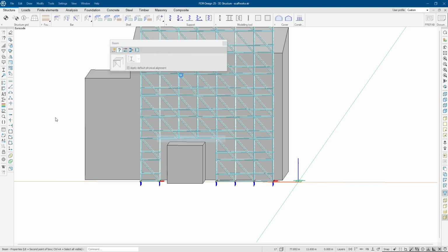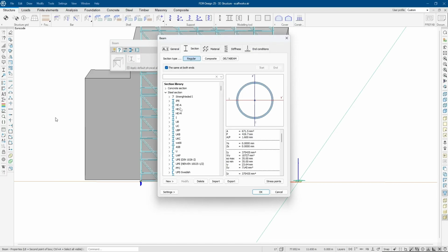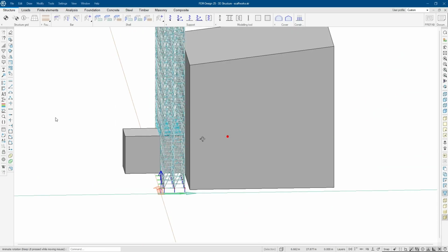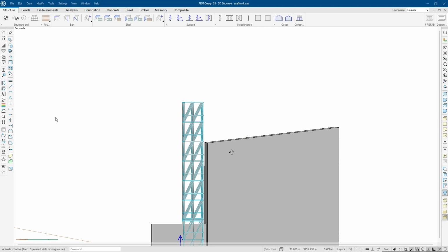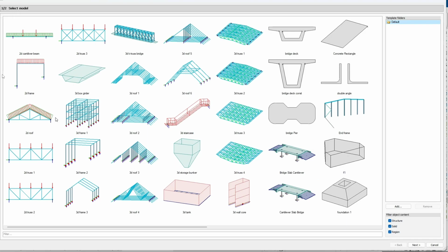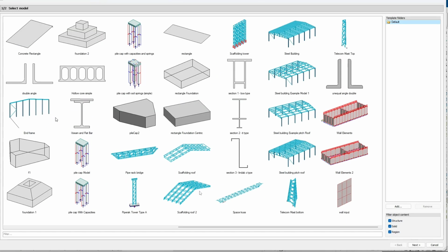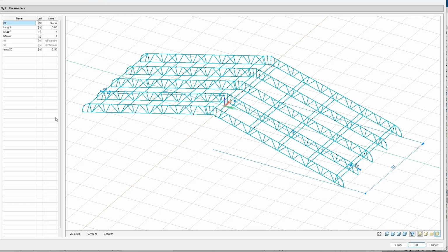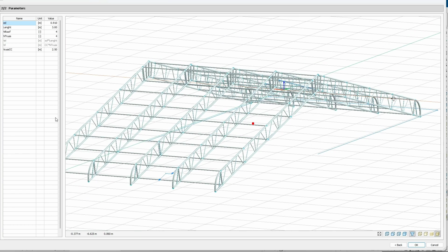So you don't have to try to make this opening in your scaffolding model. Just take the basic block and modify those parts which are not repeating. Maybe you want to have a narrow tower in the top, so you can do it like this. Do not try to make it so that you have this tapered part in the top. It's easy to make a basic block, just delete the unnecessary elements and make a roof as an element. And same here, the basic roof as an element.